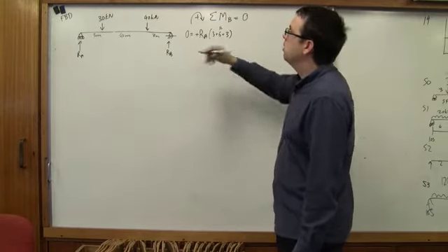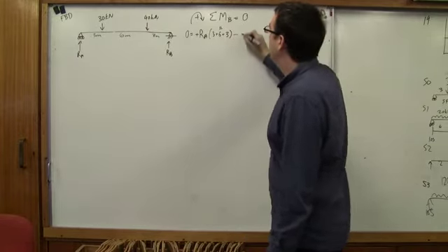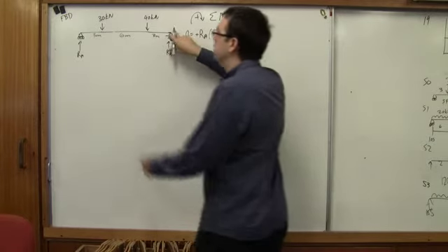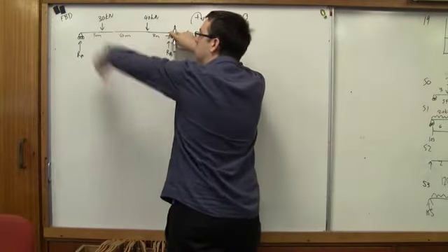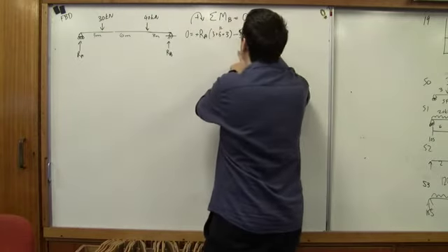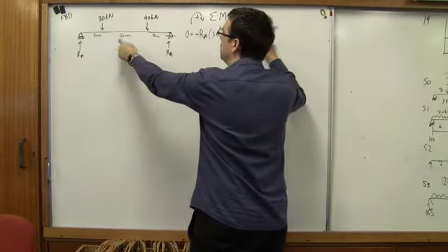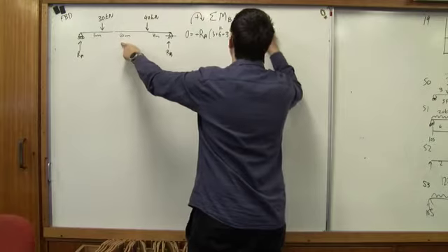Okay. The next force is we have 30. Now, is that going, relative to B, if this is a hand of a clock, clockwise or anti-clockwise? Anti-clockwise. So we're going to keep that as minus. And what's the distance away? 6. Nope. 9. 9. Excellent.